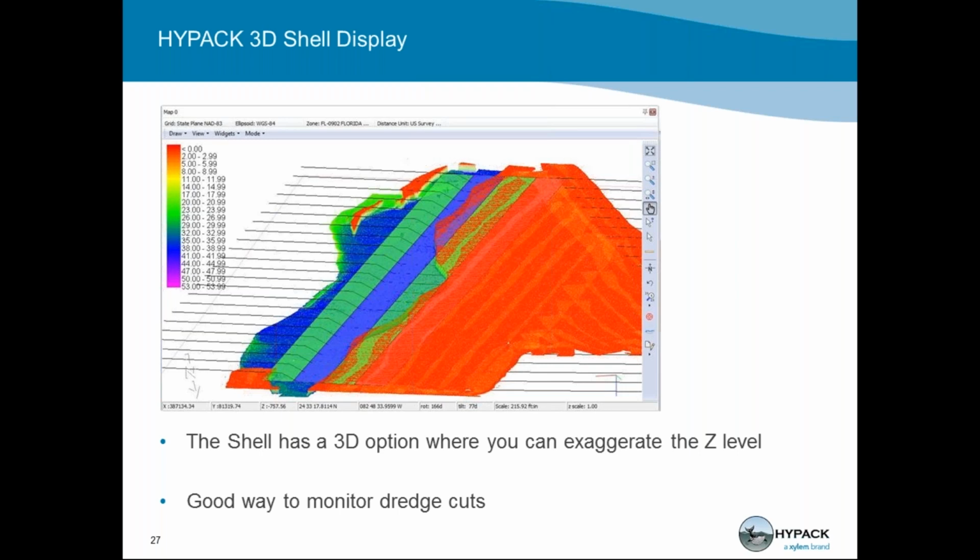So it's really helpful. A good example of using this would be if you have an XYZ file and you run that XYZ file through TIN model. A lot of people don't know you can save out a CHN out of TIN model. It can be used in DREDGEPACK to make zones out of those small little faces. This is a neat tool to make zones out of all those little faces so that when you go run volumes, you don't have volume versus face. Now you have volumes versus zone. So give it a try. And HYPACK 2019 should be available for you.